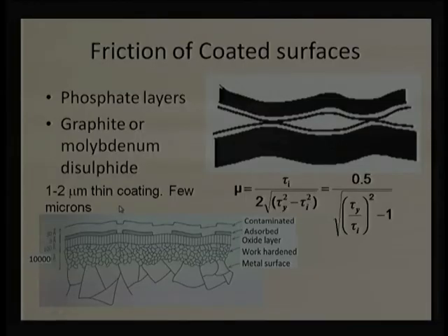Now, if there is a liquid lubricant, what would the liquid lubricant do? It can carry those powder form along with it, and it can be replenished or used again and again. So, there will always be some constant thickness layer, depending on the physical equilibrium, chemical equilibrium, and that is advantageous. Often we say a 1 to 2 micron thin solid lubricant layer is sufficient. We do not require more than that.